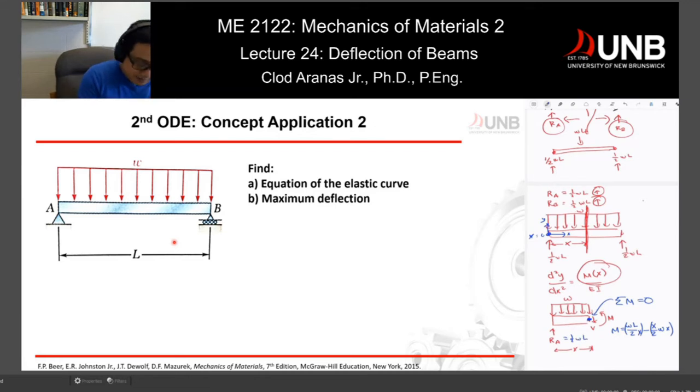So from the end of the beam, I have this full length of my beam up to point A. So I have x times whatever r sub A is, and that's kind of a negative number. You can easily imagine that I just transpose it from there, but that's a negative number. So that's 1/2 WL times x, my first term for my moment.